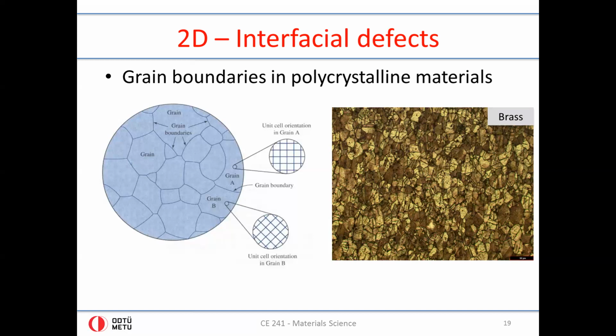You would not be able to grow the crystals so that they all have the same exact size, like shown here. Some of the crystals will end up being smaller, and some of them will be larger, and some of them will be even larger, but they will be randomly shaped, and they will have some sort of average size. And if the average size is smaller or larger, the properties of this so-called same material, iron, will differ.